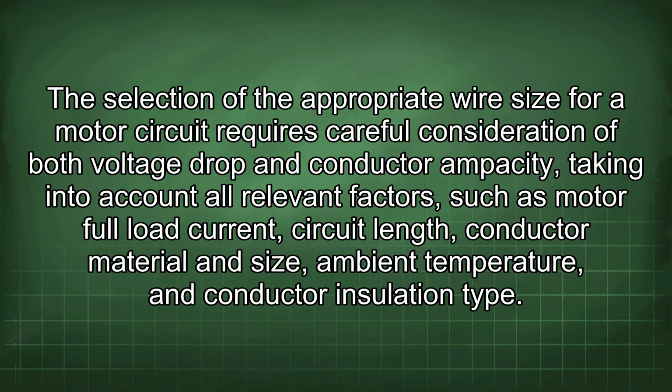The selection of the appropriate wire size for a motor circuit requires careful consideration of both voltage drop and conductor ampacity, taking into account all relevant factors such as motor full load current, circuit length, conductor material and size, ambient temperature, and conductor insulation type.